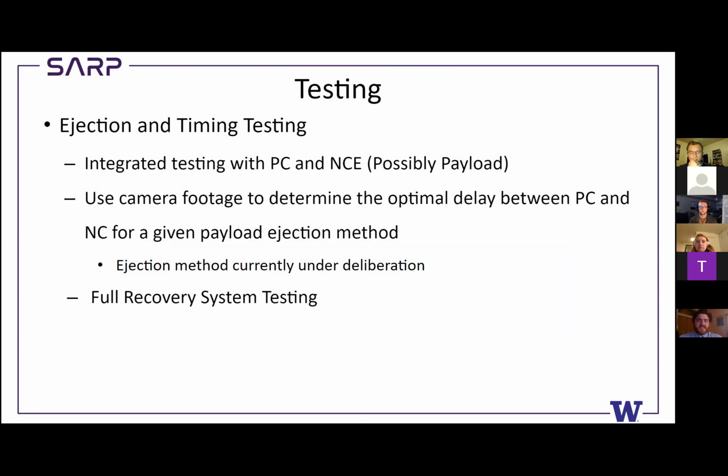And then the last thing we'll be doing, in preparation for the recovery portion of our project, is testing with Payload Coupler, Nosecone, and potentially Payload. We will use a camera to determine the optimal delay between fuses between Payload Coupler and Nosecone for a given payload ejection method.